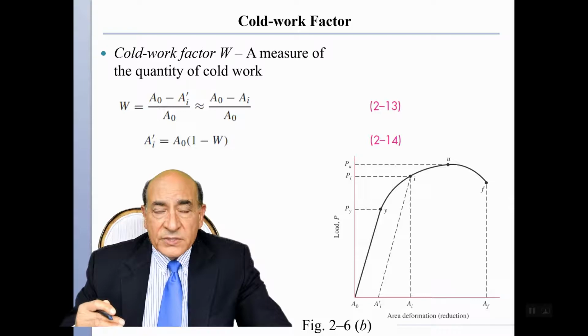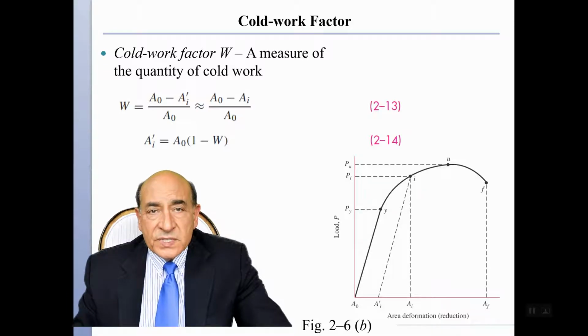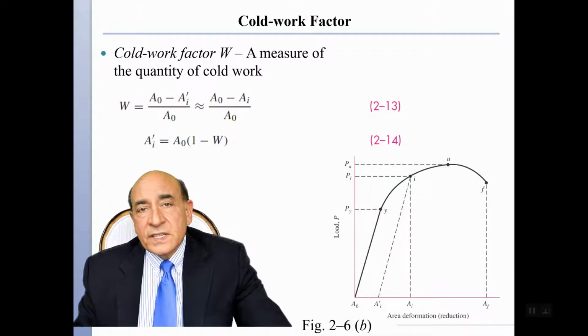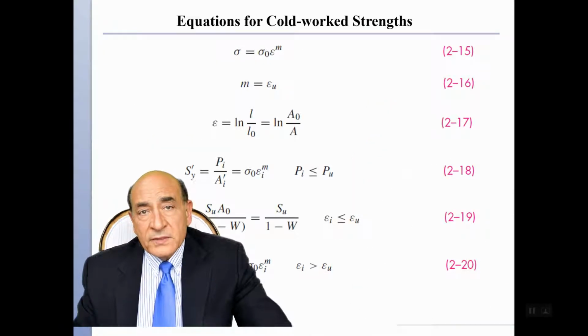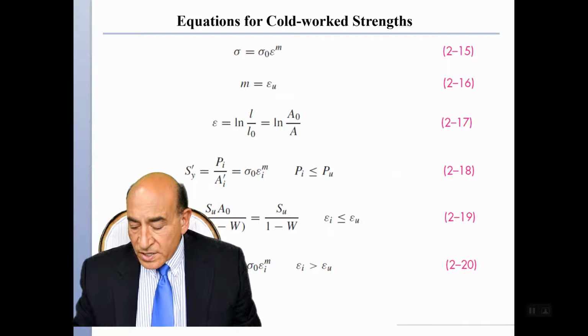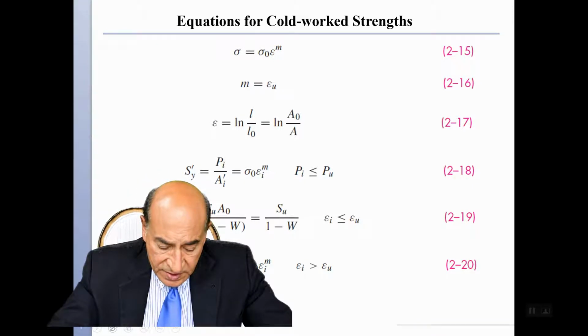Suppose now we come back to the idea of cold work. How do we define the degree of cold work, and how do we use it to estimate the new value of the yield strength? And is the new value of the yield strength greater than the old value? If yes, then we have achieved hardening of the material, making it harder and stronger. So for the cold work situation here, let me describe it as the following. So the cold work is going to be described as, let's say, the degree of cold work.